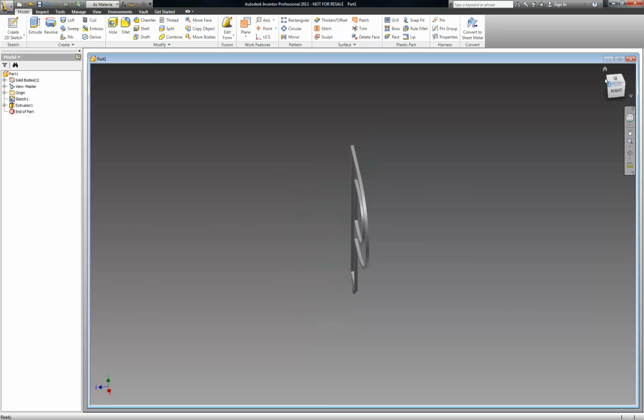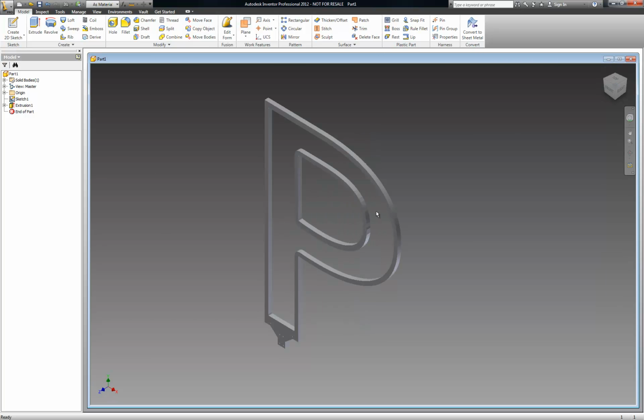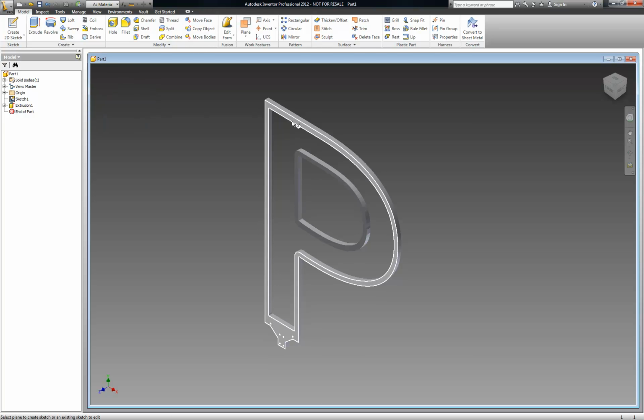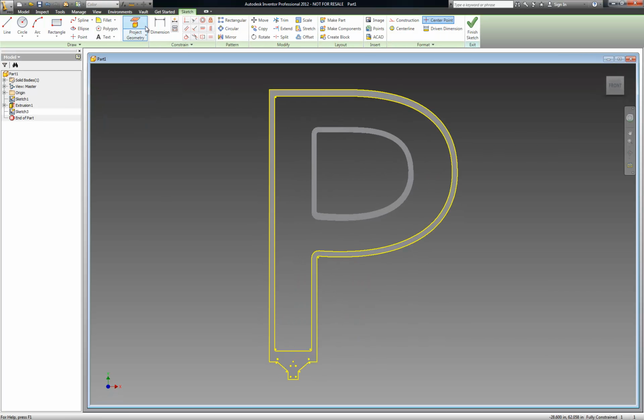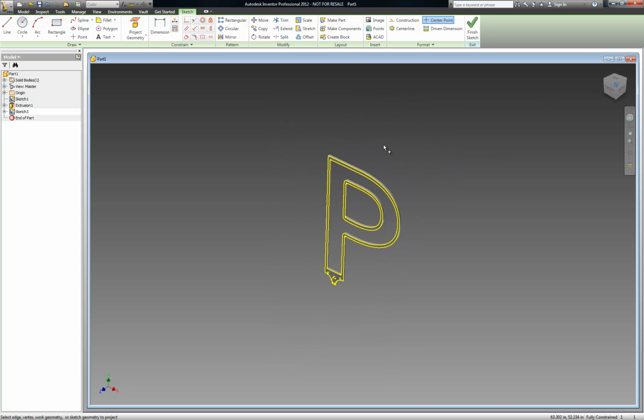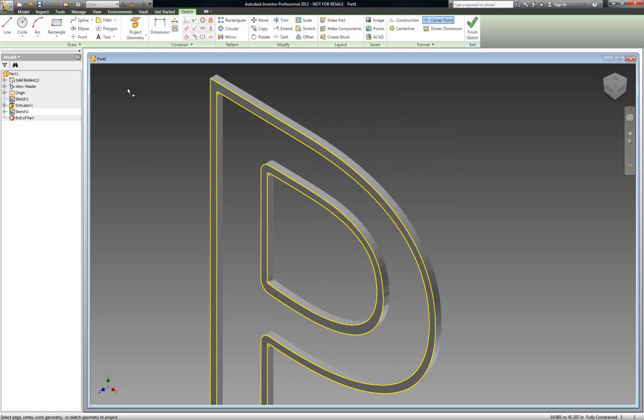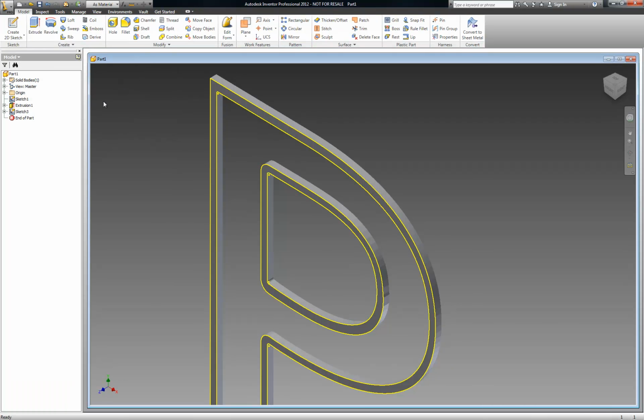and this is the front here. So I guess I'll do my surface on that. So I'm going to right click, New Sketch. I'm going to pick this surface. Okay. I'm going to go Project Geometry, project that geometry and that geometry. Okay. Now here's the fun part. I'm going to go Finish Sketch.